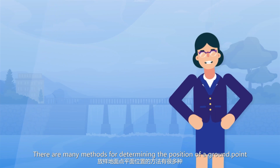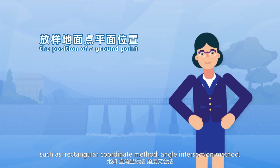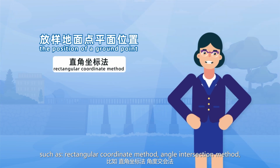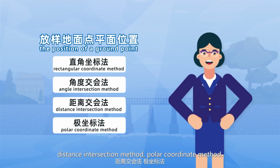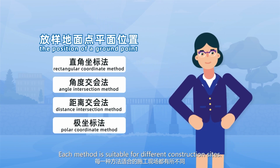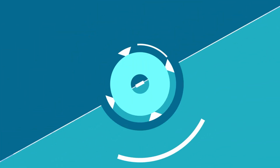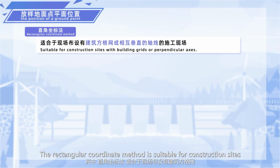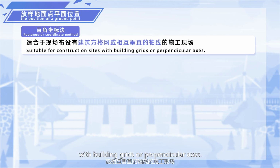There are many methods for determining the position of a ground point, such as the rectangular coordinate method, angle intersection method, distance intersection method, and polar coordinate method. Each method is suitable for different construction sites. The rectangular coordinate method is suitable for construction sites with building grids or perpendicular axes.